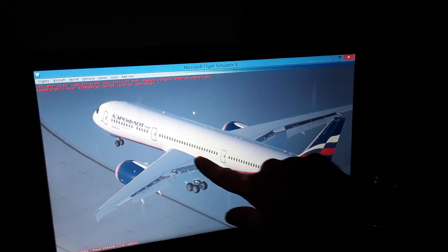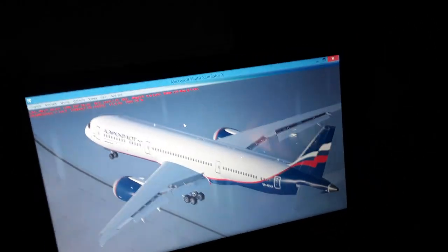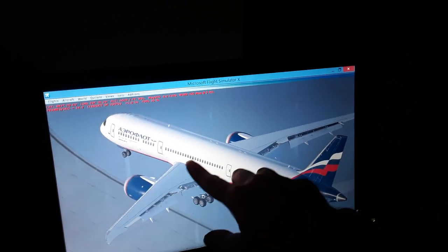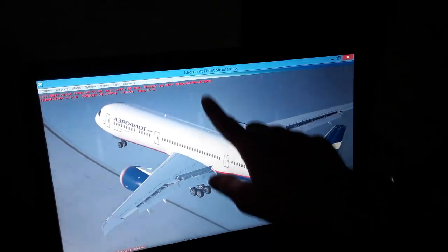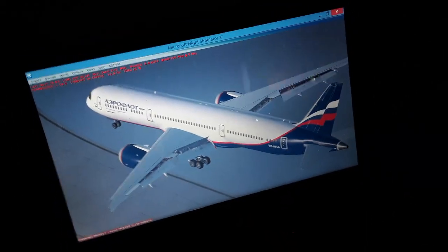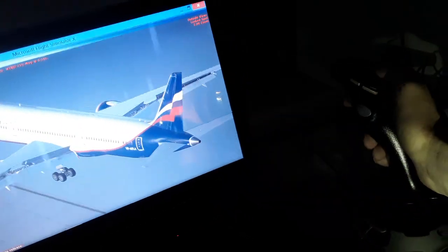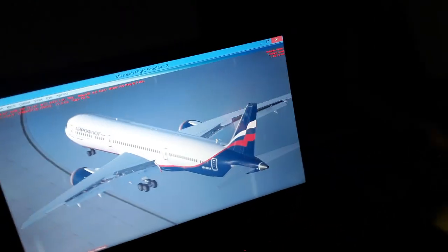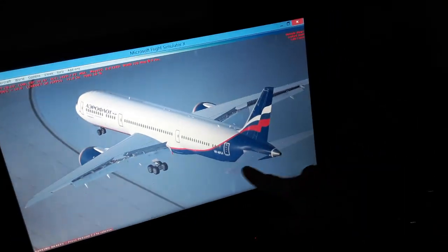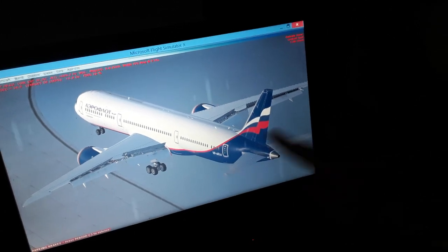Also, it's the center of pressure here, moving forward or aft. Also, where the mean aerodynamic chord, where the maximum aerodynamic lift occurs in the wings, is where usually is the center of gravity of the aircraft, the vertical axis of the aircraft. So we have also the lateral axis from wingtip to wingtip. The lateral axis is the pitch axis of the aircraft, so you can climb and you can descend the aircraft around. The vertical axis is the yawing axis, and the longitudinal from nose to tail. Also the horizontal trim stabilizer and the elevator through the pitch axis. So we have the roll axis over here. We can roll the aircraft like this.